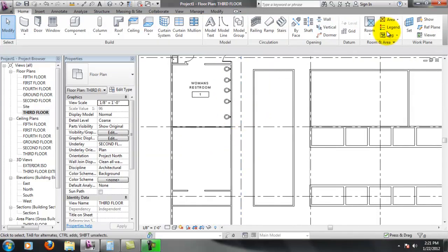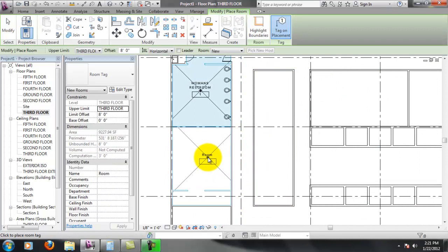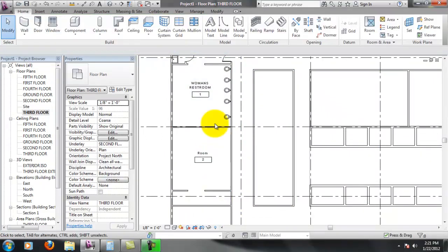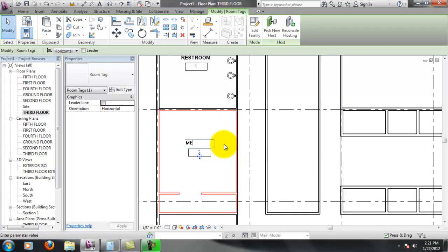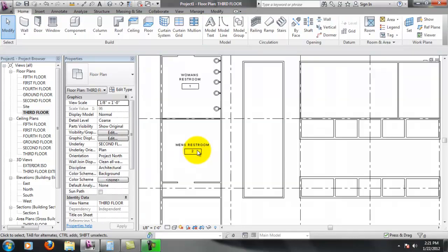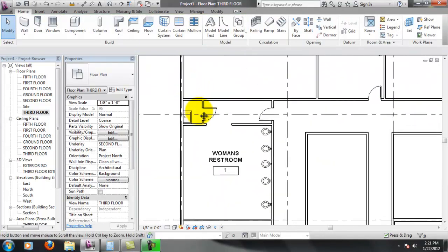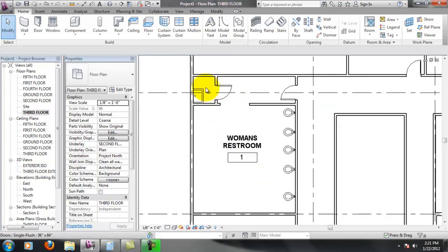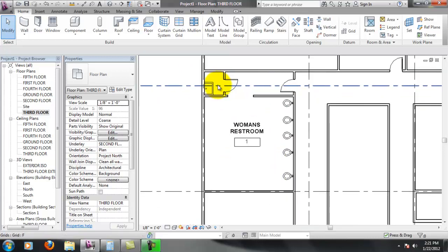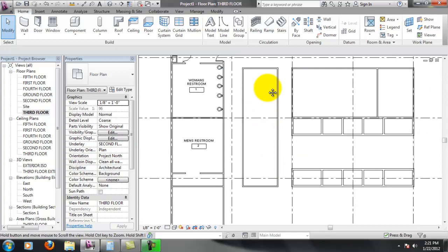All right, that's simple. And then I'm going to hit room again and come down here and select again. Notice by default 1, 2, it'll automatically count all the way around. We'll talk about subtags for rooms like this inside of rooms. This shouldn't necessarily have its own room tag. It should be more like 1B maybe. We'll talk about that as we progress through the project.